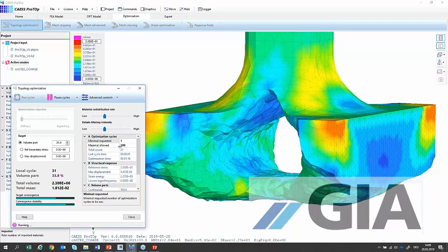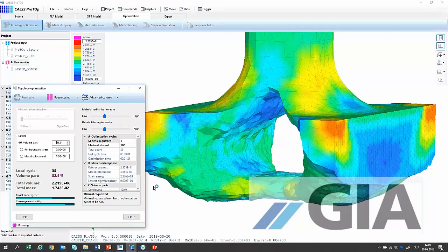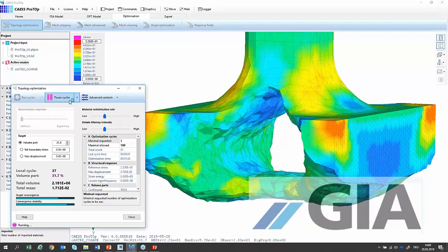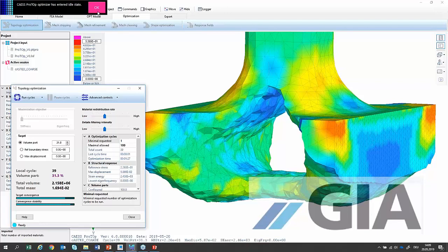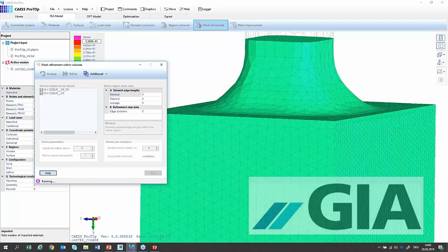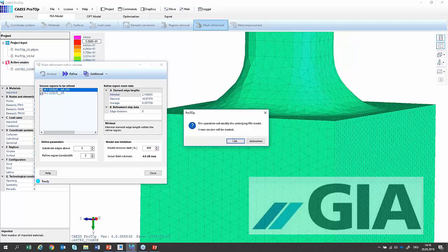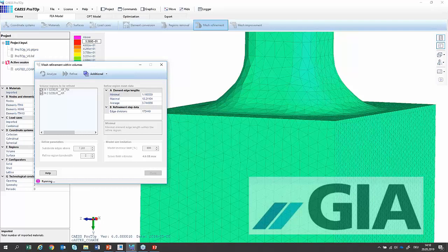Of course, at the end of the day, we want to have nearly perfect surfaces. Therefore, I will do the mesh refinement again. I'm stopping the optimization right now, FEA model, do the mesh refinement again, analyze it, and do the mesh refinement around 5 millimeters and a certain amount of RAM. Going to redefine it, a new instance will be created, and now it's getting interesting for the casting companies.